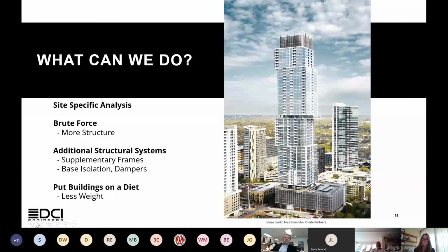Typically what they'll do is go out, they'll take their site borings, do the shear wave analysis, and determine the site class from there. However, doing a site-specific analysis is a much more rigorous analysis on the geotechnical end, so that is an option that we'll have to determine upfront as to whether there is enough savings in terms of lateral loads to perform that analysis.